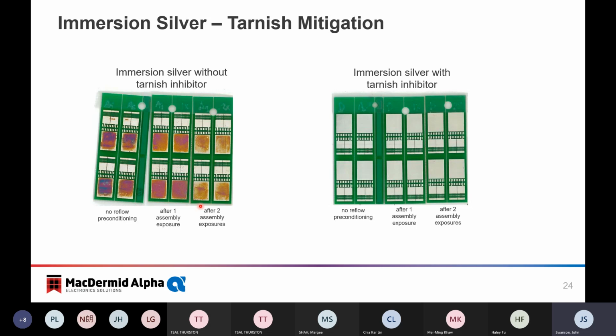Now, there are more extreme types of corrosion that can happen with exposure to sulfide and acid gases and humidity that present some risk with silver. So we want to be clear that silver in excessively polluted environments with high sulfide levels, high H2S levels, and humidity can be a problem. And this is one of the limitations of silver. We can stop basic tarnish, but aggressive forms of corrosion that can occur in highly polluted environments can be a concern.